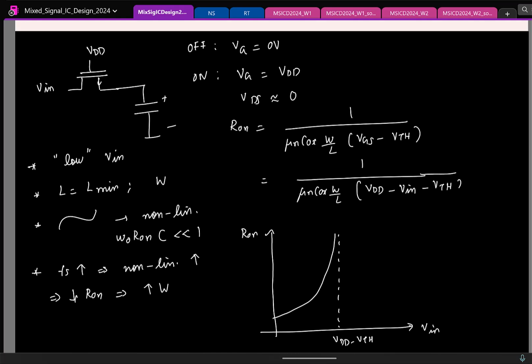Even if you don't know the MOS device construction, if I increase the area, capacitance is directly proportional to area. Overall capacitance will increase, right? In principle, at all the nodes, it's going to increase. But let us say this is driven by an ideal voltage source. You put an elephant here, nothing changes. So let us say the capacitance here is already large enough that any extra capacitance you add is not an issue. So here is where the other capacitance is.